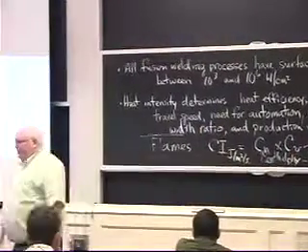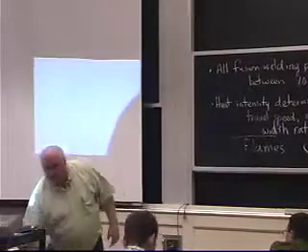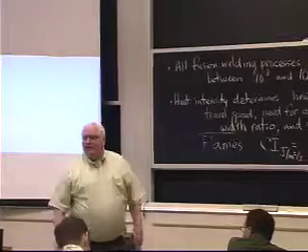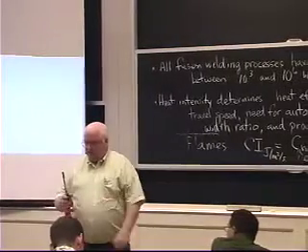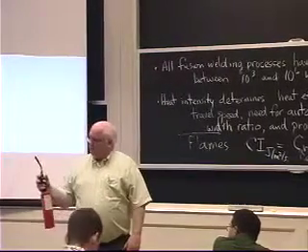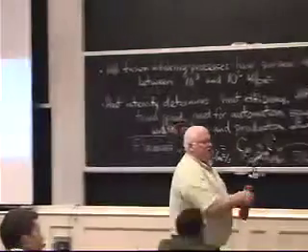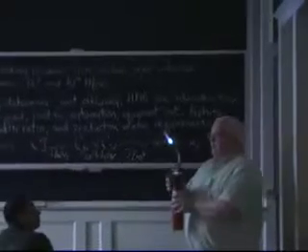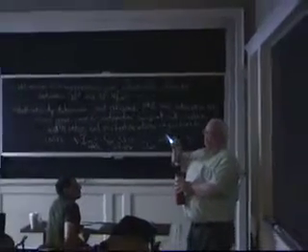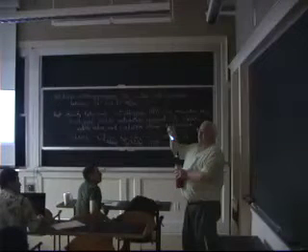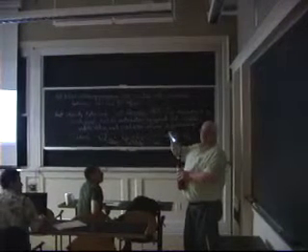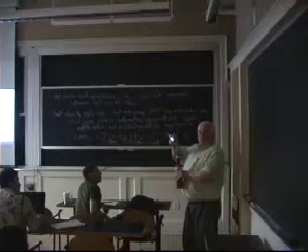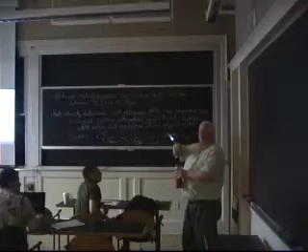Now, has anyone ever heard of burning velocity? Some of you guys have dealt with explosives. You've heard of explosive velocities and things like that, right? In fact, if I take the torch, and I may have to turn the lights off to make this a little bit easier. But right now, the gas coming out is faster than the combustion velocity. Otherwise, if the combustion velocity was faster than the gas, it would burn back.